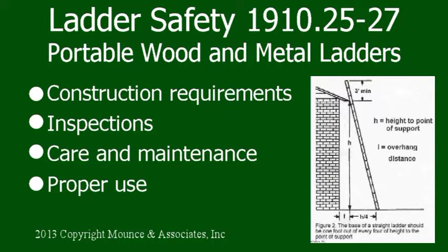When using the ladder, the proper way to set it up is at an angle. This angle must use a distance from the vertical wall equal to 1/4 the working length of the ladder, as demonstrated in this image.